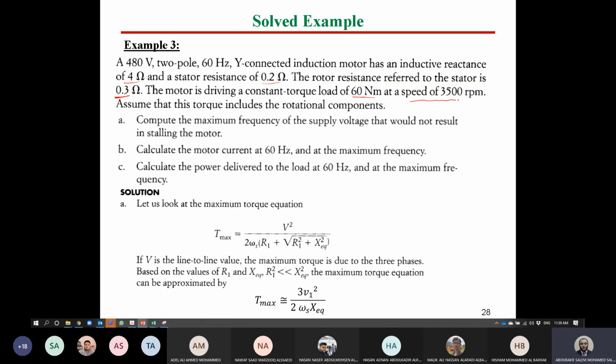So what is this speed now, guys? What is this speed? Faisal, please. This is the rotor speed. At which operating condition? Now we read here a speed of 3500. What is exactly this speed? The rated speed. Rated speed, bravo, excellent. So this is now the full load or rated speed of our motor. At which conditions? At the condition of supplying the machine by 60 hertz and rated voltage.